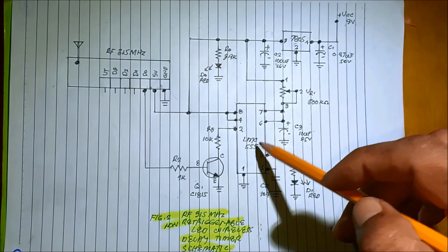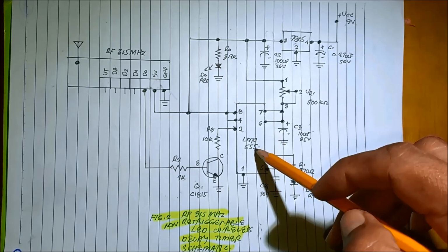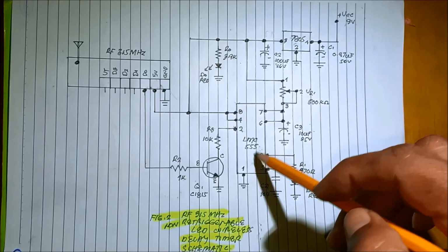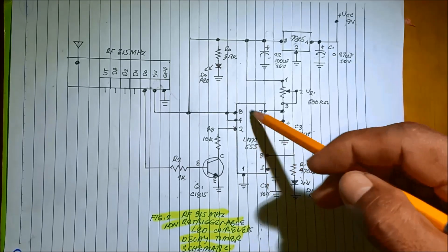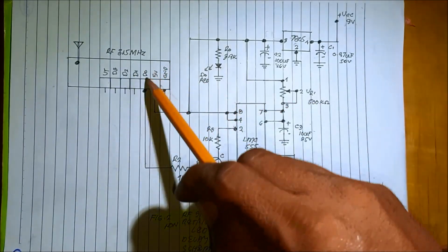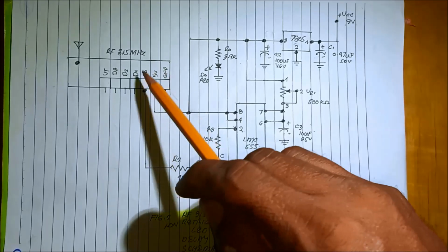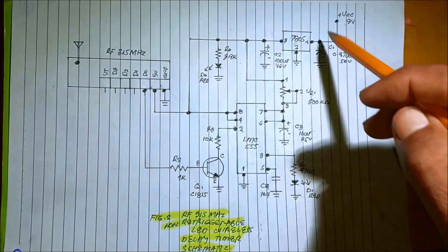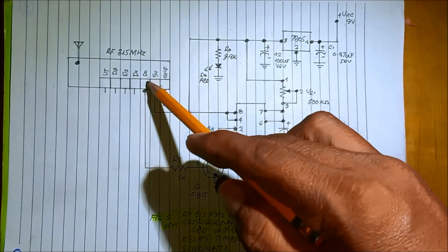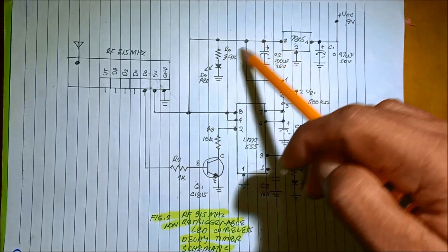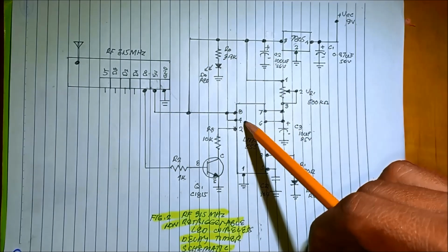The use of this LMC 555 timer is as a monostable, or a delay timer, for the LED. And this one is a wireless switch, or radio frequency wireless switch, RF module. And then also powering this receiver, 5 volts then to the ground, powering also this 555 timer.